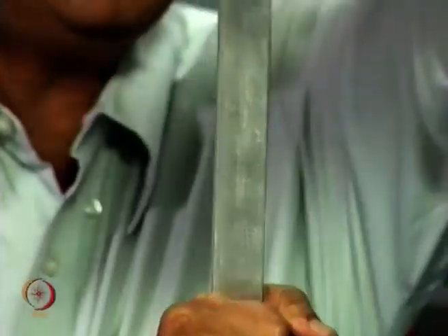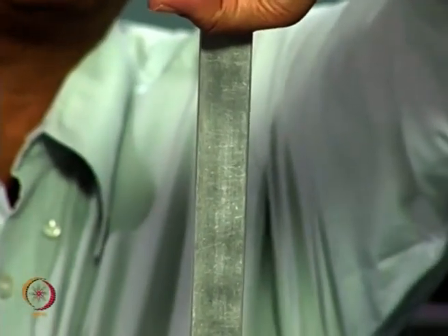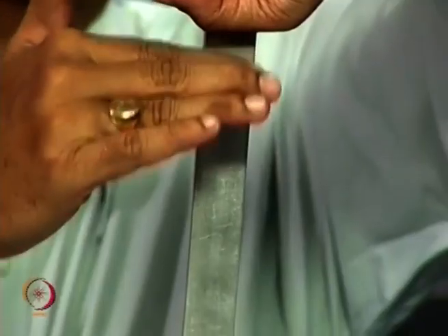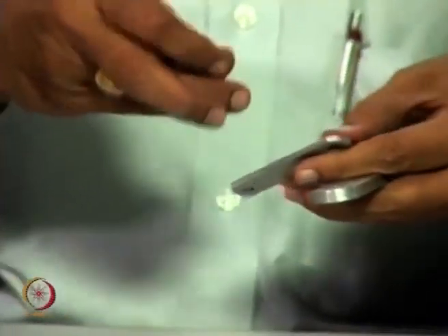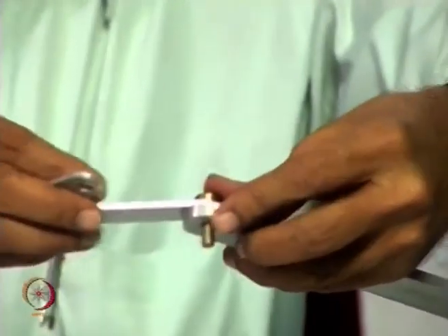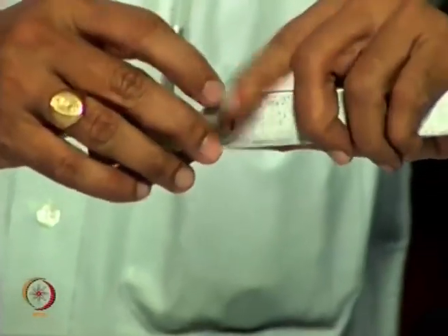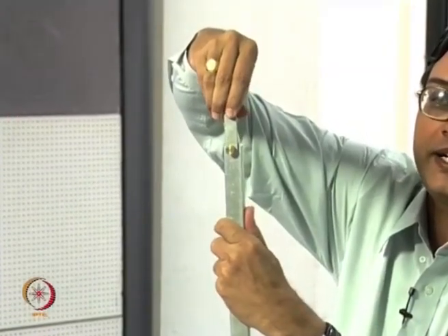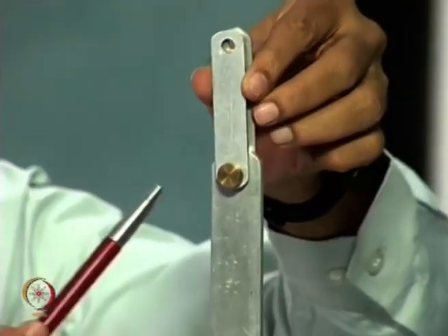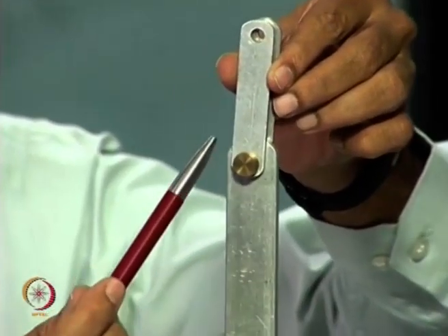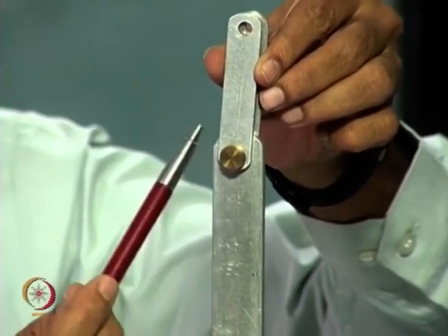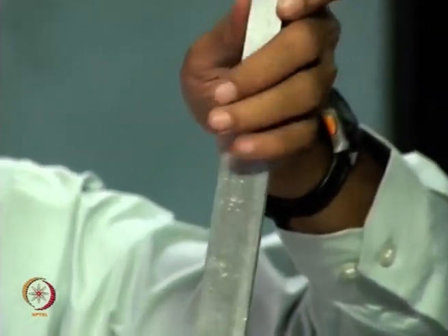Now, let us see one simple example. I have this rod and I want to pull it. I can pull it by grips. I can have solid grips and then pull the rod, and I can also pull the rod by another method, which is what we usually do. You have a sling, you have a pin, so you pull it with the pin. It also has a certain level of self alignment, and if you look at the stress distribution in the close vicinity of the hole, and the way I grip it, these two are different.